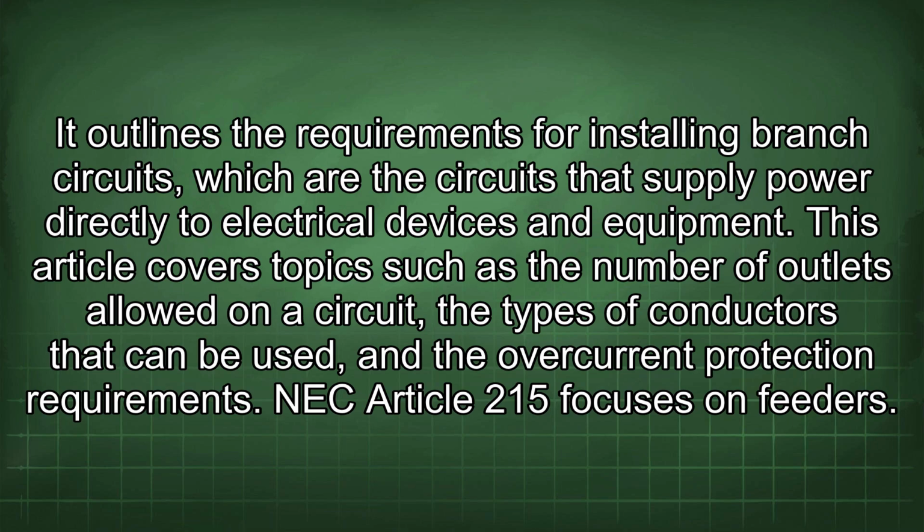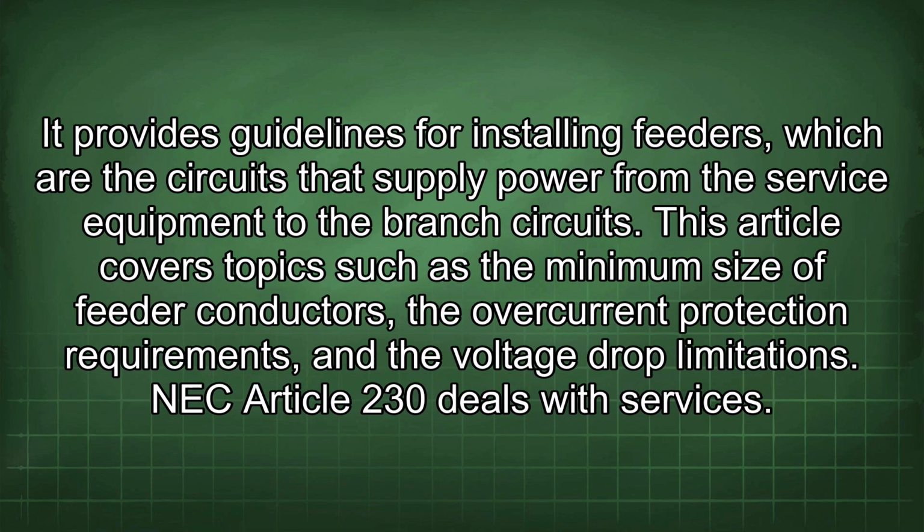NEC Article 215 focuses on feeders. It provides guidelines for installing feeders, which are the circuits that supply power from the service equipment to the branch circuits. This article covers topics such as the minimum size of feeder conductors, the overcurrent protection requirements, and the voltage drop limitations.